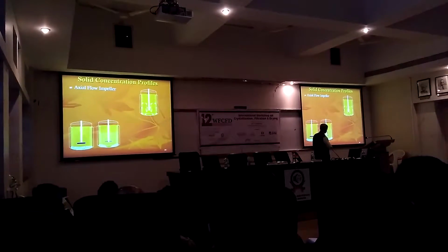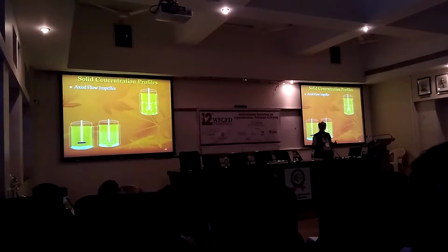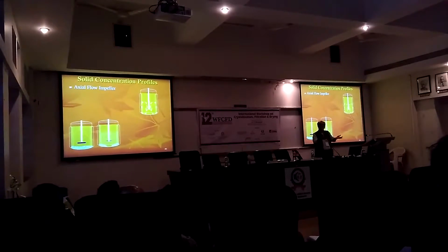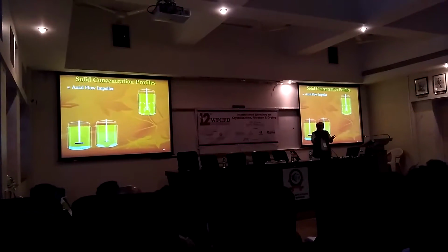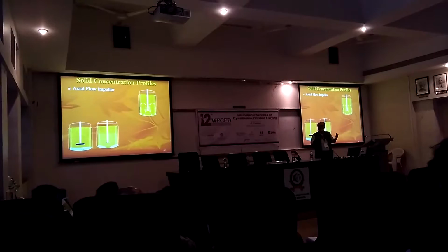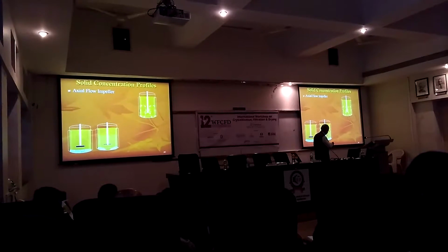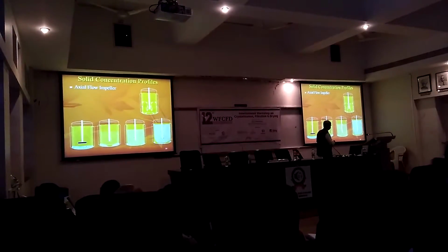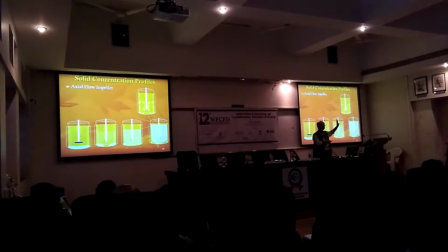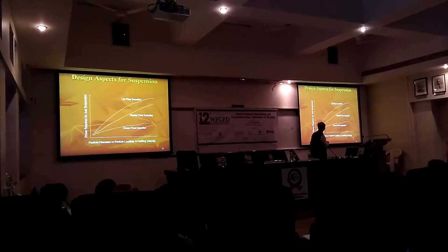You get dead ends at this. Now there have been very clever designs where the bottoms of these particular crystallizers have been punched out in such a way that these dead zones are avoided. As a result of which you don't see any dead mass accumulated in these corners. Increasing impeller speed ultimately makes the particle suspension complete.